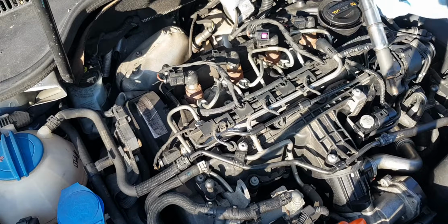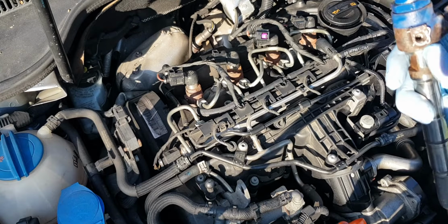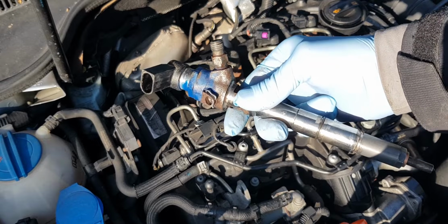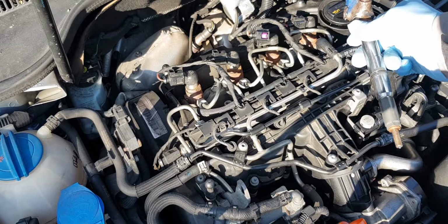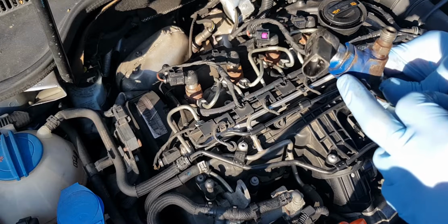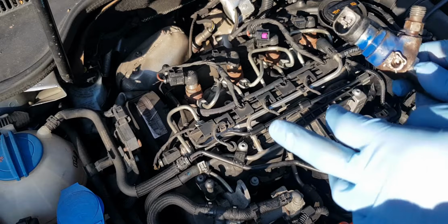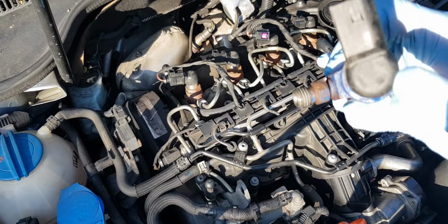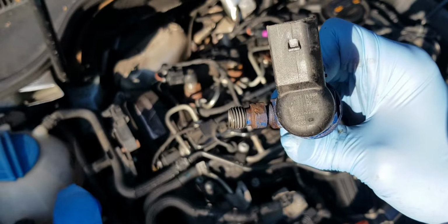This is the new-ish second-hand injector that I'm gonna install. And if you're curious like myself, you're wondering what's going to happen if you plug this in here and read the faults and try to erase them. Obviously, being a good injector, I have checked the resistance on these 2 pins and it's 200 kilo ohms, so it matches the same as the other 3 injectors, 1, 2 and 4, and it's exactly the same. It is exactly the same part number as well, 277B.